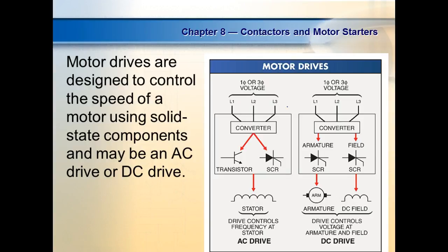So what would happen if you lost the connection to the field while the motor's running? It'll speed up and run away. Yeah, it'll run away. So that's why normally on these motors we don't fool with the field. We leave it.